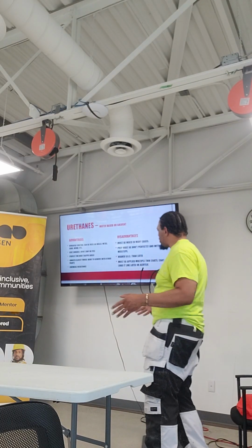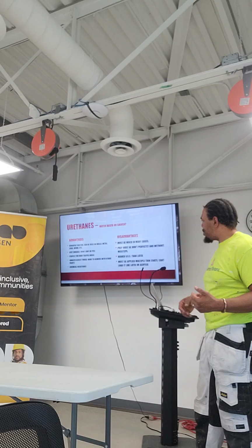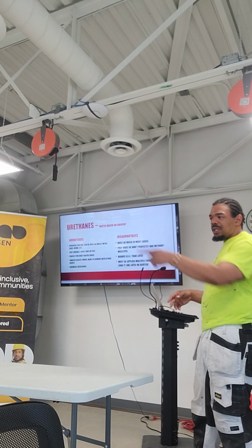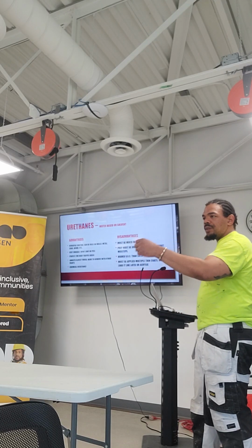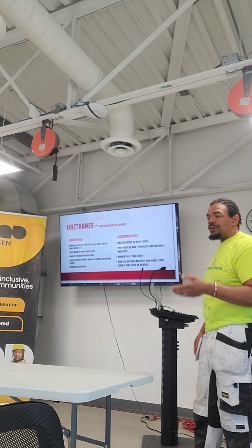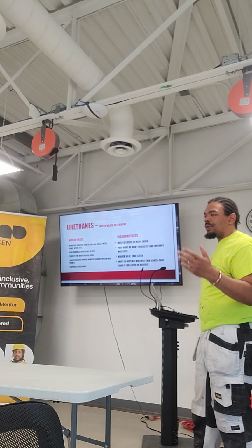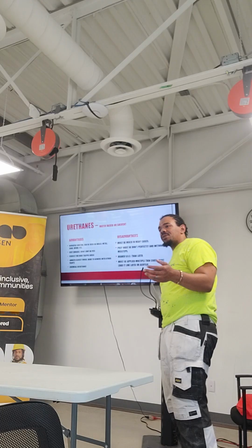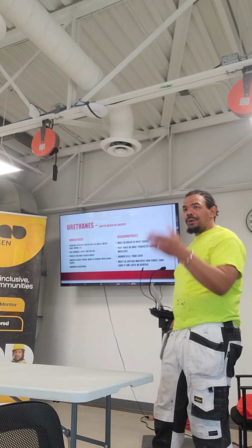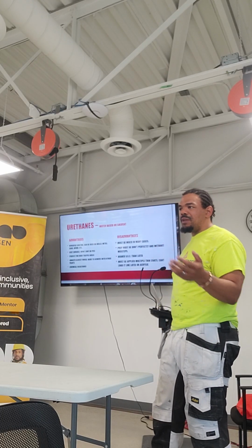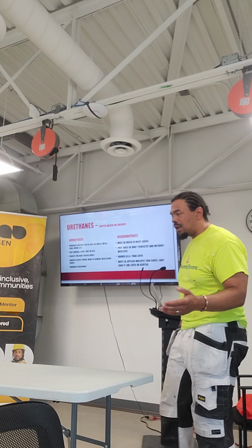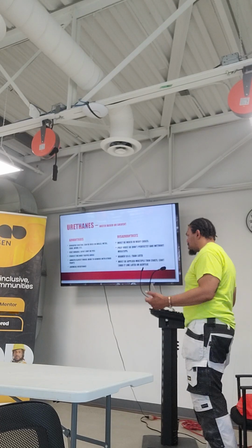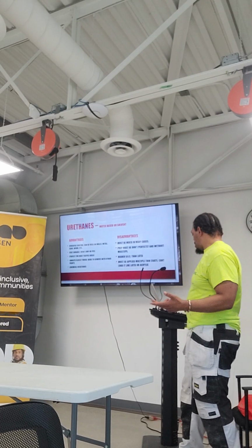So it's perfect for those high traffic areas. It won't chip or peel. And again, you can use it on just about any surface that you can think of. So this is MDF, you can use a urethane. That's a polyurethane. You can use a urethane coating on metal. You can use it on glass. You can use it on this Stix primer that we demoed yesterday. That's a urethane coating. That's how it's able to bind to glass, PVC, and all these types of surfaces. So these are some of the advantages of urethanes. You can get a urethane water-based coating as well as a solvent coating.